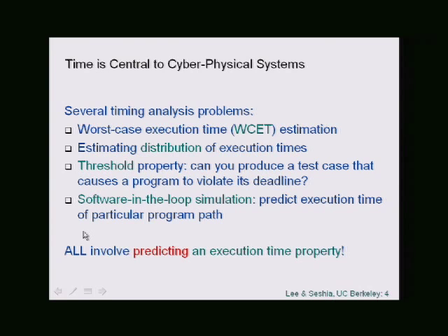Okay? So many physical quantities are relevant for the correctness of embedded systems or cyber-physical systems, but time is one of them which really stands out. So that's going to be the focus of today's lecture. But a lot of the ideas we talk about today will also apply to things like estimating energy consumption of a program running on a given platform. Okay, so there are several timing analysis or timing verification questions that arise in practice. Perhaps the most common one is something called worst case execution time estimation, WCET.